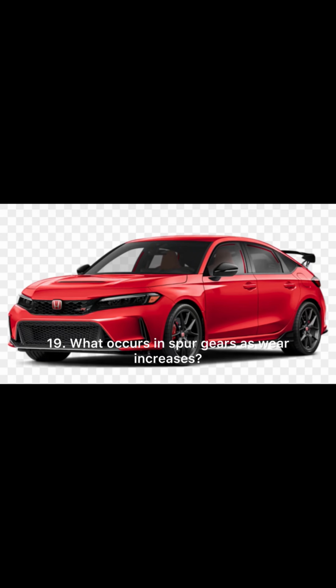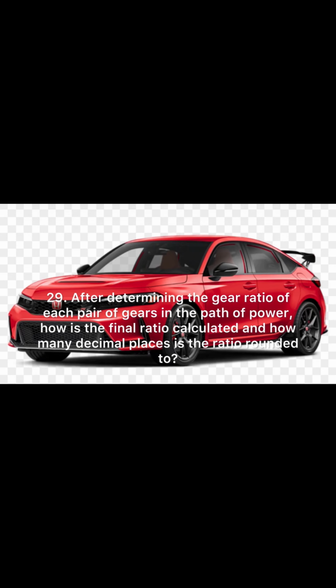28. Why did manufacturers add an overdrive to the manual transmissions? Fuel economy, emissions, NVH. 29. After determining the gear ratio of each pair of gears in the path of power, how is the final ratio calculated and to how many decimal places is the ratio rounded? Ratios are multiplied, to two decimal places.